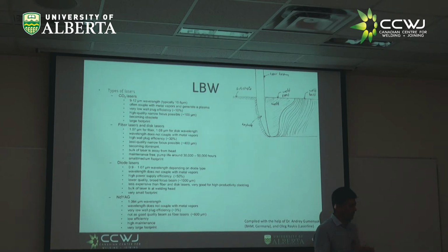At 1 micron, I can make an optic fiber that delivers the light like a hose, and it's extremely practical. But that optic fiber is not transparent at 10 microns. So how are you going to move the light from your laser to the part? You start bouncing it on mirrors. That's the reason. You could do mirrors with the other ones too, but that defeats the point.